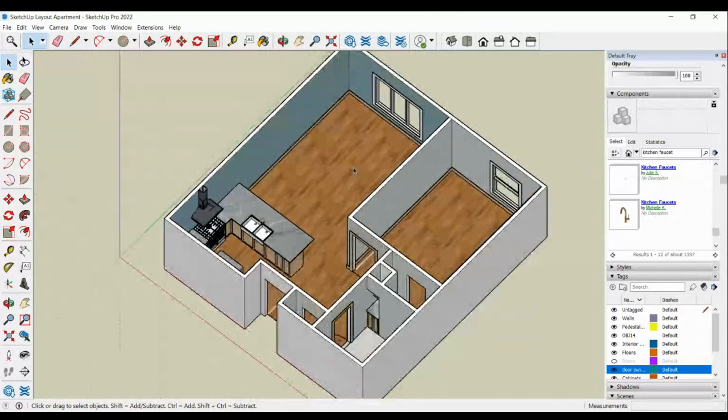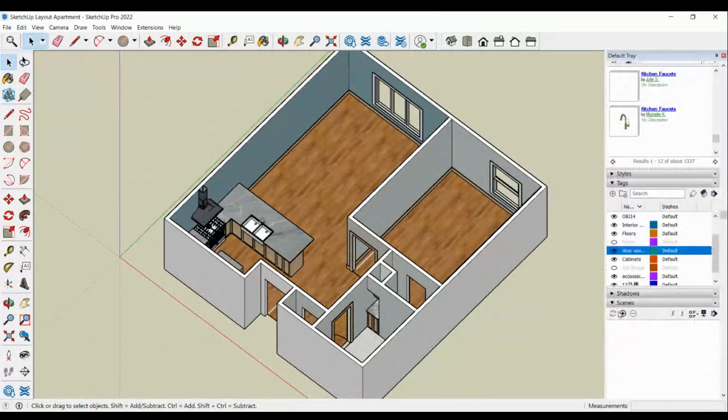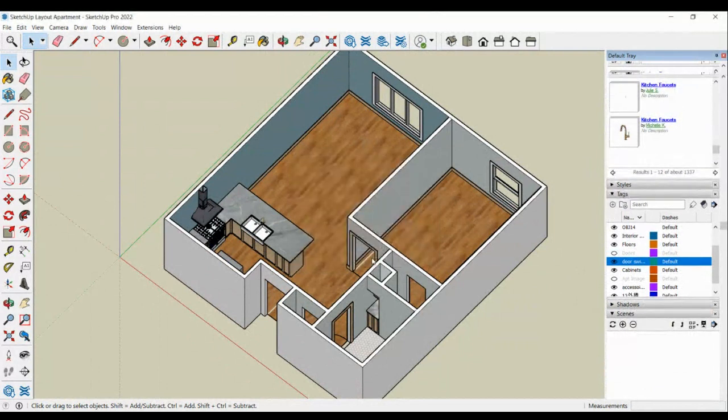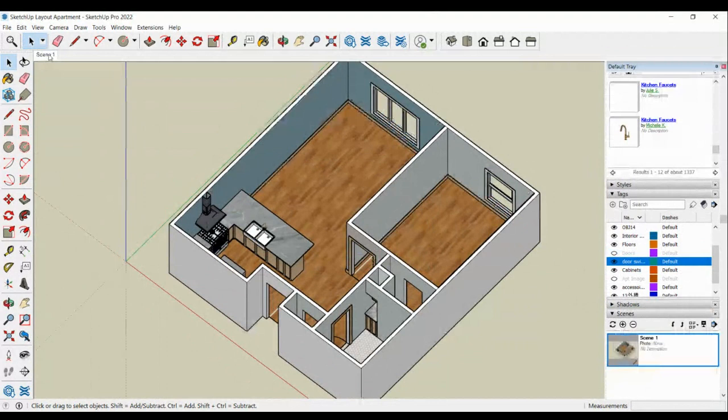And so with that, you're going to be creating scenes for each of the drawings that you want. So think of the scenes kind of as the viewports that you're going to want to put on your title blocks. Typically, I'll go to scenes and I'll add a first one, just hit create scene. And lots of times, it'll come up here, there's a tab and it says scene 1. If you right click on that and hit rename, you can rename it.